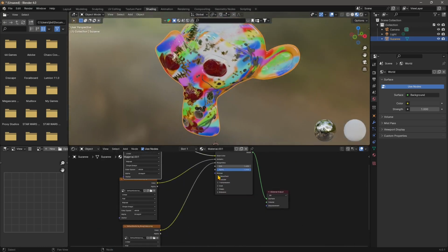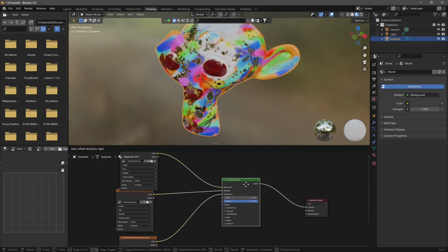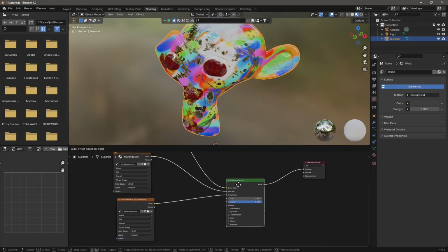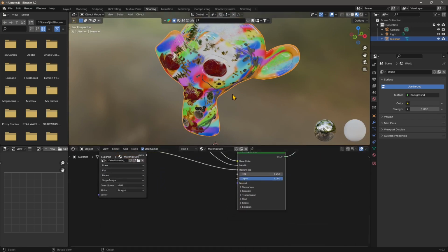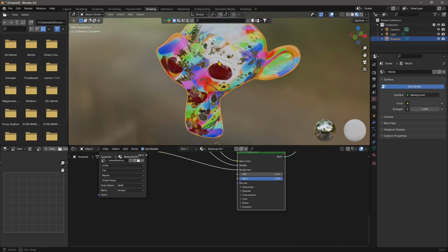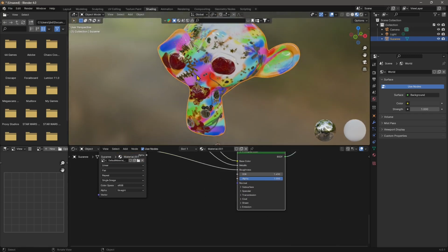We're only missing the normals, which are a fake 3D effect. You can use real 3D extrusion here using the displacement, but this is covered in another video guide. Here I'm just going to use the fake and light normal maps. So I'm going to click and drag this out. And before I get the texture, I need to add also a normal map node like this.